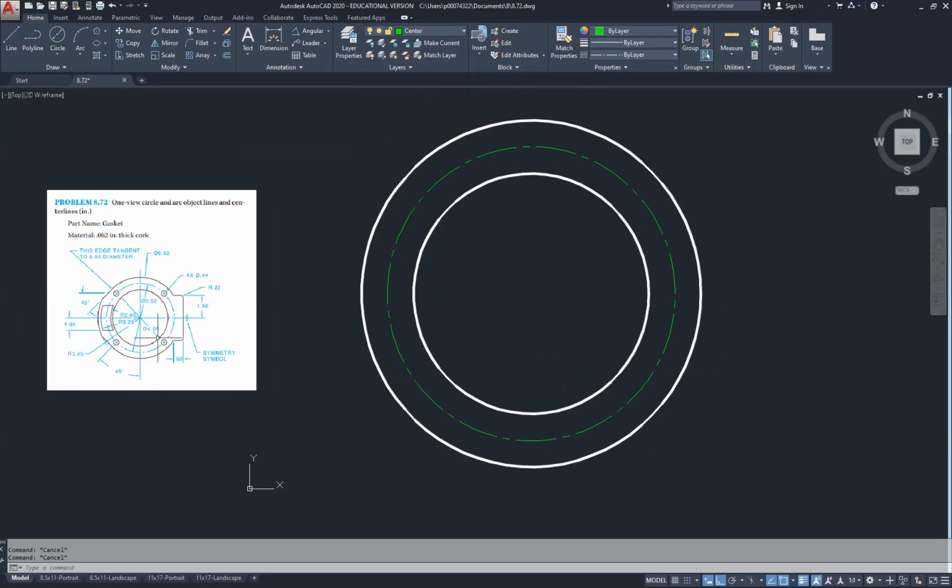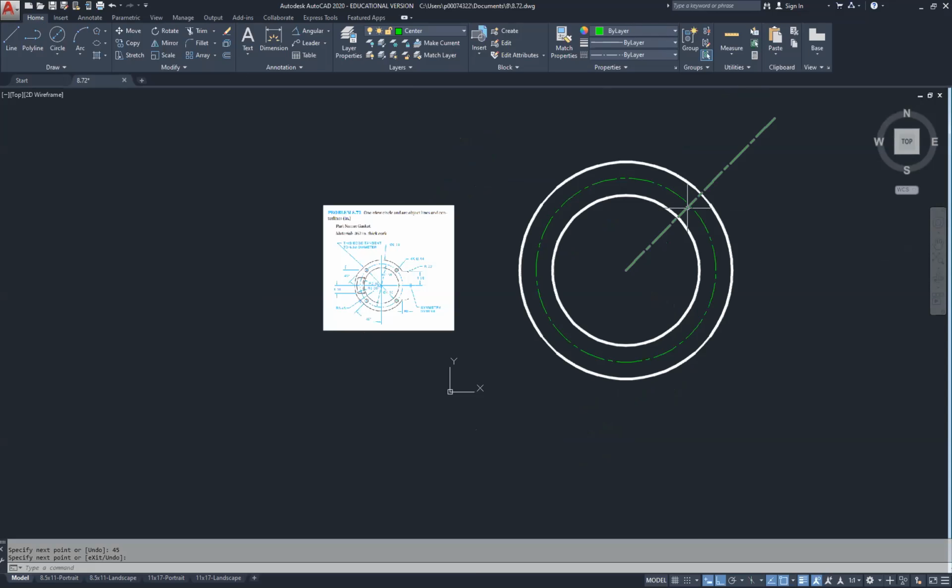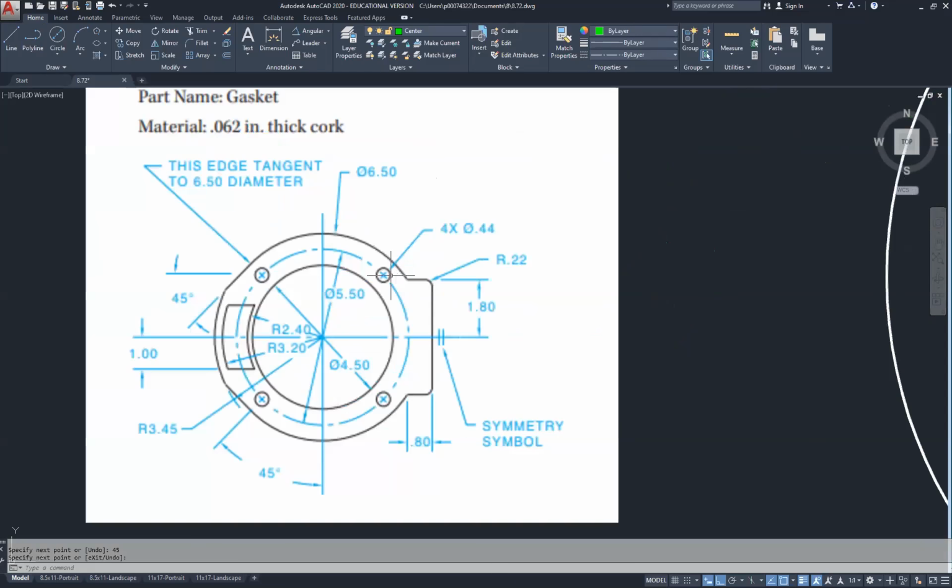So just for construction purposes, let's go ahead and get the diagonals that we have here, here, and here. They're all going to be at 45 degrees. So what I'm going to do is draw a line from here, coming straight across. The distance doesn't matter, how far out I go. I'm going to hit the Tab key. And you notice that it changes to my degrees. I know this is going to be 45 degrees. And then just hit enter. And there's my first location for my first hole here.